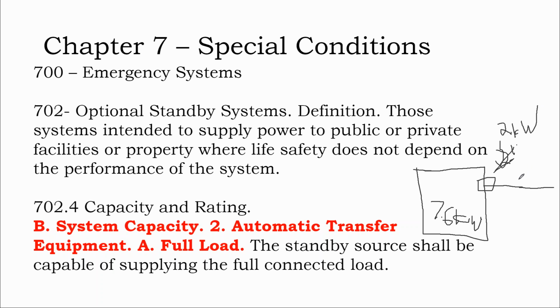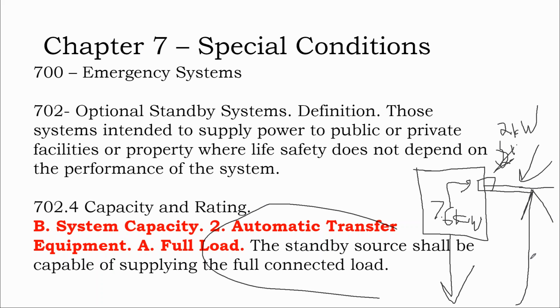Or like with the Tesla Powerwall, the power goes out, and the Tesla Powerwall doesn't back up your entire house through its output. It has a critical load side that gets transferred and runs critical loads off the critical load side. And why is that? It's because whatever loads are connected to the critical load side, code says you have to be able to power them.